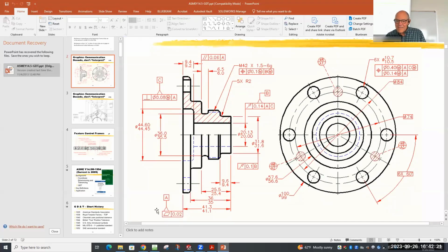So flatness, we looked at straightness. Runout means I put my needle, my dial indicator, at any given point and measure runout. And if it falls inside the tolerance, everything's fine. I pick it up, put it at some other spot and turn it, and if it's in that range, it's fine. Over here, do the same thing, but I don't compare them to each other. So runout is at a particular location.